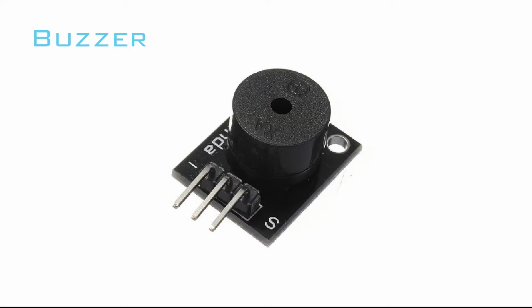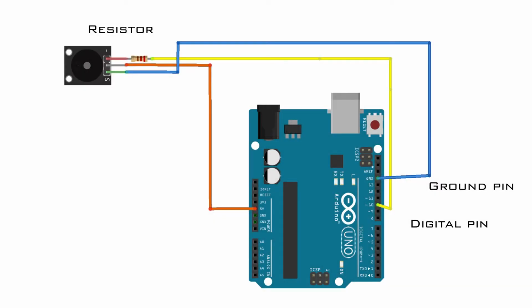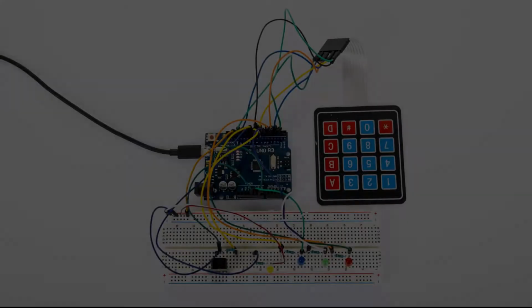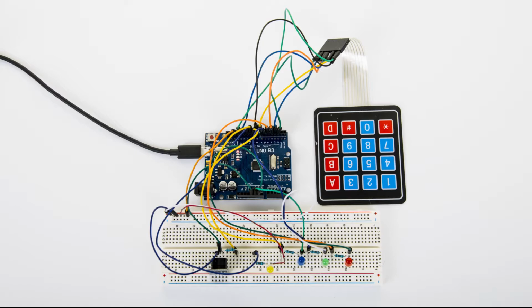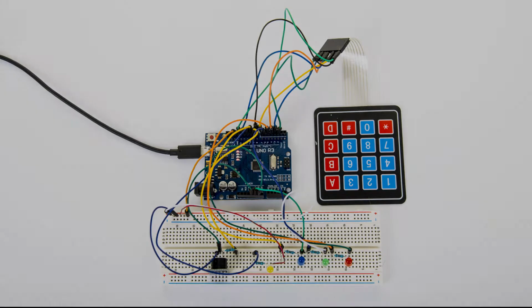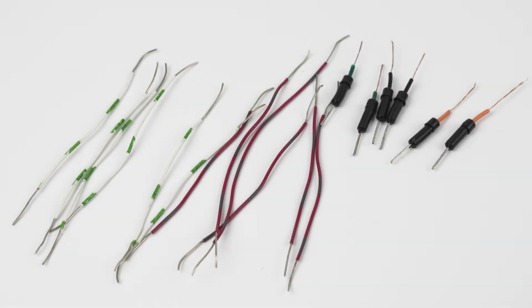The last major component used in the project is a buzzer. The buzzer used in our project is passive. We've used one 220 ohms resistor to slightly muffle the otherwise loud buzzer. All of the LEDs used in the project, the buzzer and the resistors, were soldered together with pieces of wire, making the connections permanent. Because of it, a breadboard was no longer needed in the project.